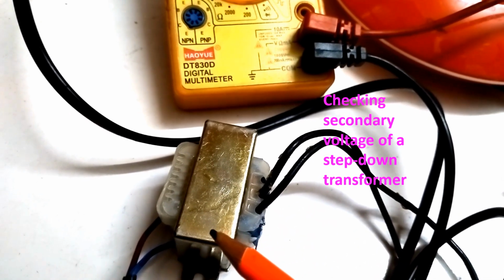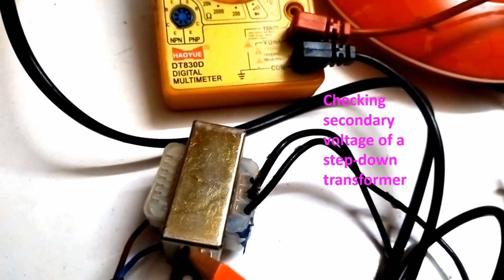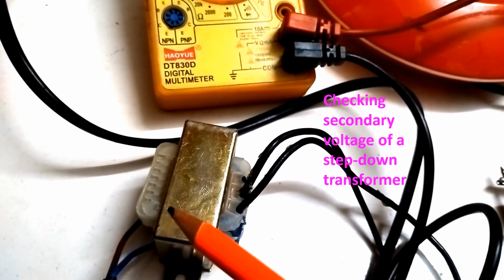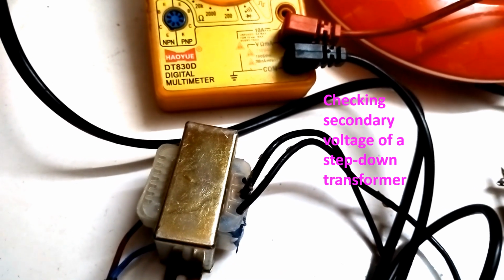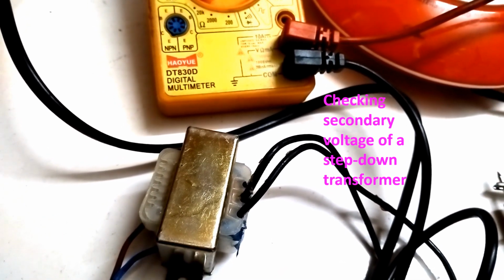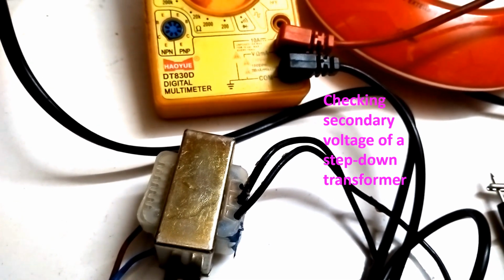The actual number of turns will not be 230, it will be much more, to have enough impedance to prevent too much current damaging the primary winding, because depending on the thickness of the wire used, you will need a higher number of turns.